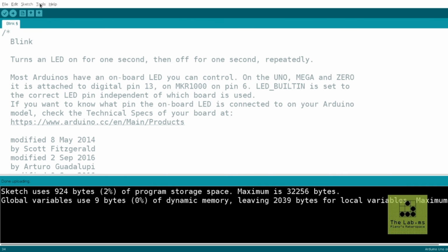All right, so we've told Arduino IDE that we're using an Arduino Uno, and we've told it which port it's on. So now we should be able to communicate with it. And by communicating, what we're doing is we're sending our code down to that board. So I have opened this Blink program, and the way you open these sketches is to go to the File menu, and you can go to Examples. From Basics, you can see Blink. So select that, and it will open up this file.